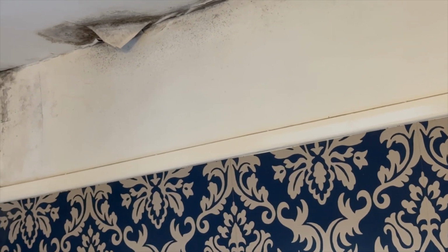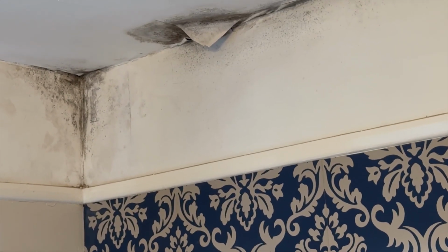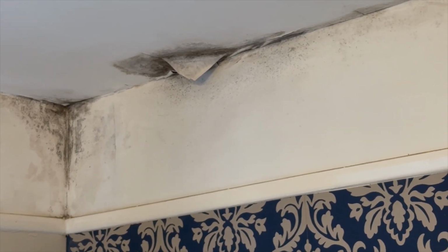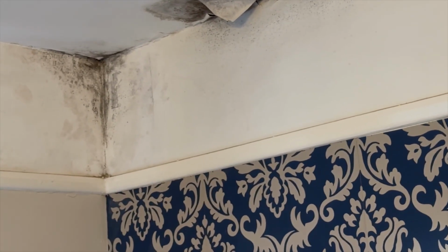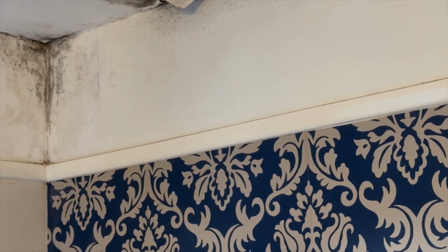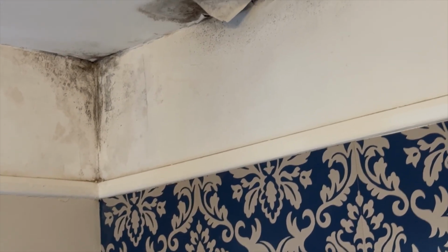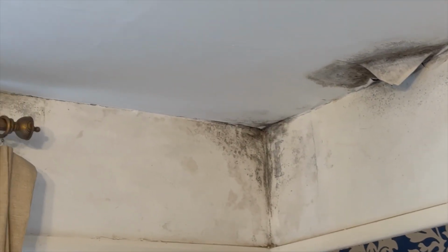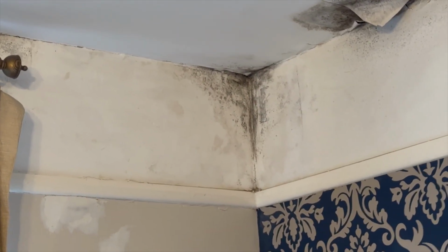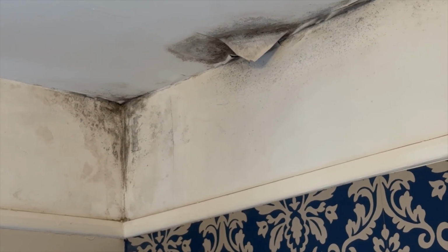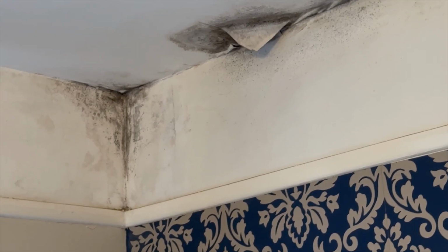Okay. And I would use HG anti-mold spray. Bleach is the active ingredient, but it has a foaming agent that keeps it on the wall for longer. Be careful not to spray onto clothing, textiles, or the wallpaper, because it could bleach it a bit. So just be careful on that, but don't go wild. But yeah, I think that's a starting point in terms of getting rid of the mold, and once you've brought the vapor levels down, it will stop growing.